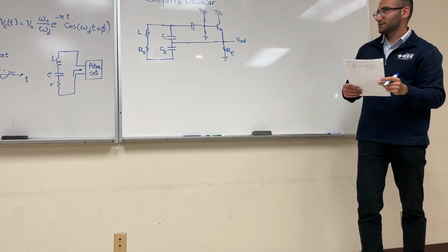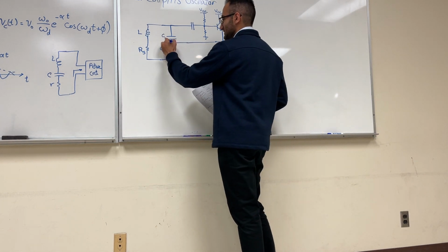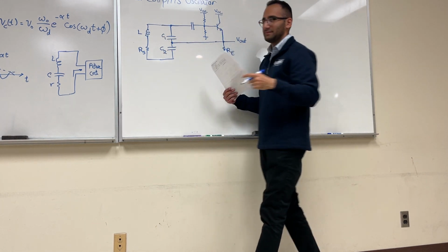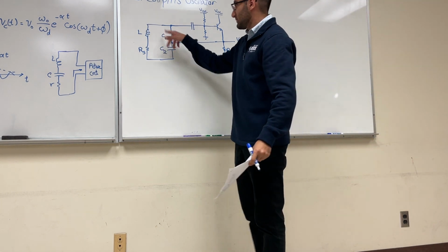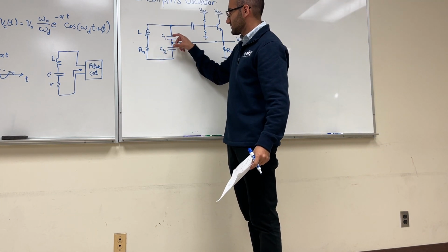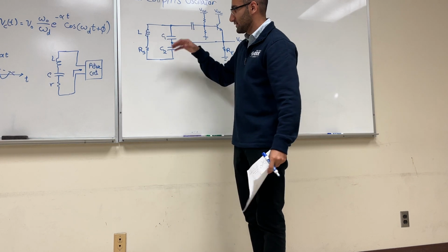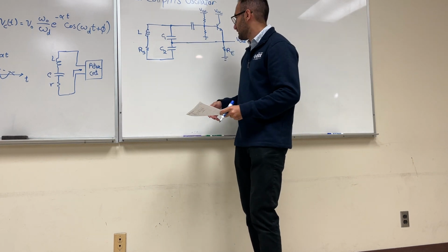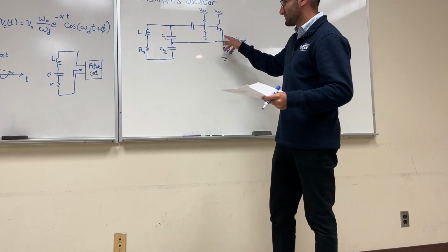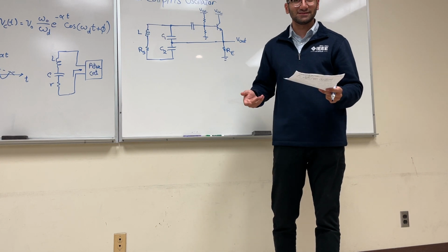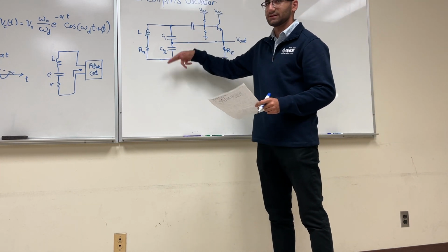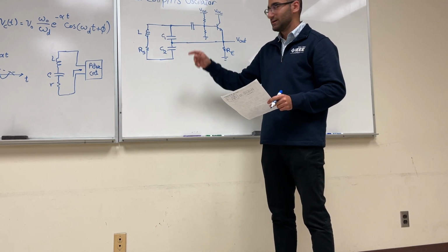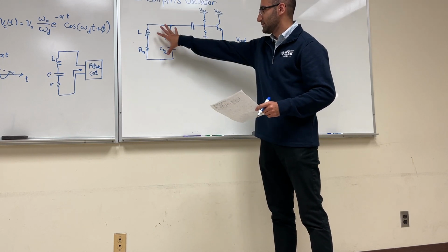Okay, so before we get into any sort of math, let's see why this even makes sense. As time goes on, the charges stored on these capacitors are going to go down. And this amplifier, which we discussed in the last session, is basically going to charge C2 constantly. So it will make sure that the charge will not go down in this LC tank.